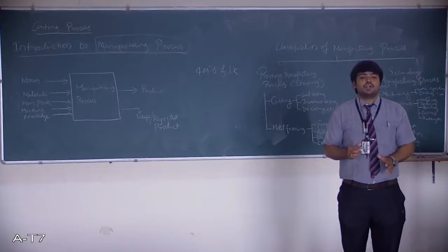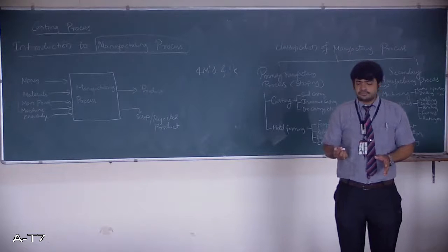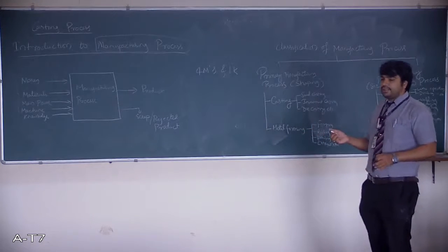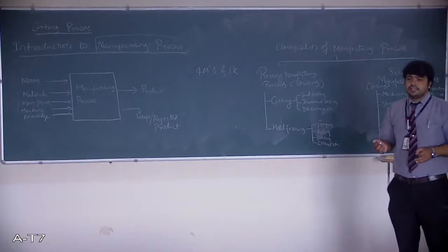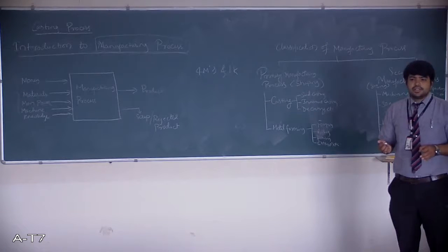That is what is called forging. Most automotive components are manufactured by this forging technology. Again, there are two different types in forging: open die forging and closed die forging. Just remember, in forging we hammer the component in its red hot condition.